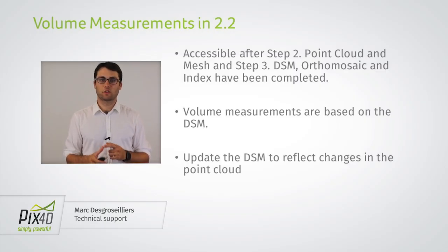The second thing to keep in mind is that if you modify the point cloud and you want these modifications to be reflected in the volume measurements, you will need to regenerate the DSM, that is, for example, run step 3 again, to make sure that these modifications are taken into account and that the volume measurements are updated.